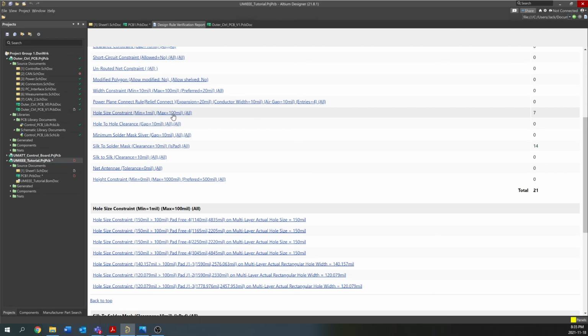So the best thing to do in this case, I'm not going to do it today, is to fix that and put in the actual value for your manufacturer so that it properly checks it. You wouldn't just ignore it, because we have 7 violations. If you had 100 violations, you're not going to go through and check each one. You want to change the hole size constraint and run another design rule check against that.